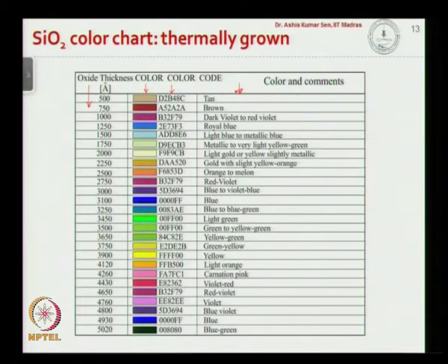So typically you oxidize a wafer, take it out of the oxidation furnace, and you can have a look. There will be a color chart available. Depending on how you judge the color, you can predict the thickness of the oxidation layer, okay.